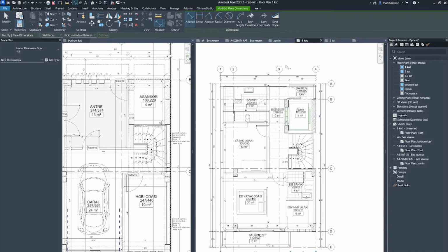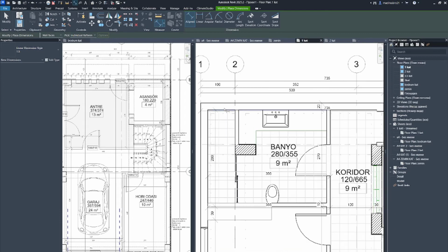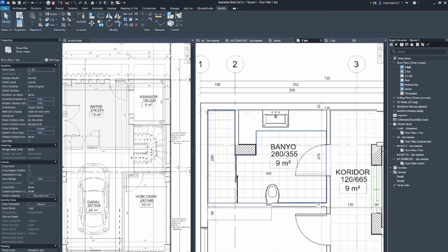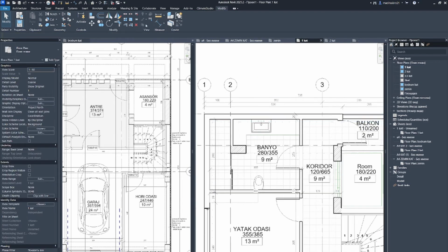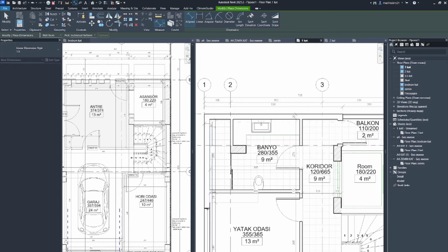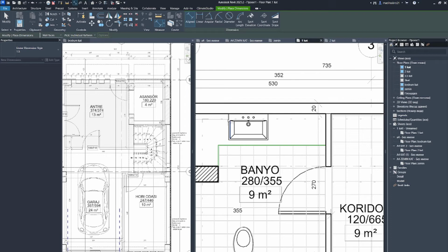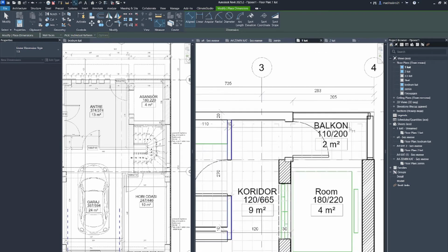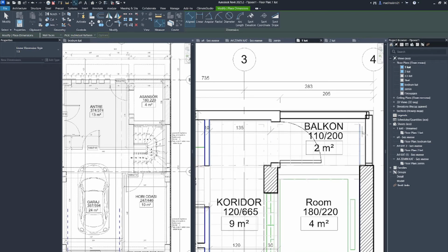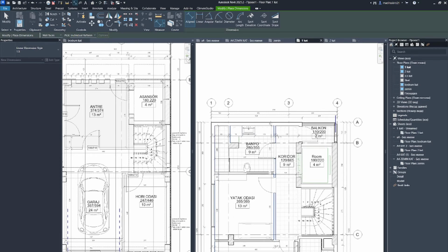Now we're going to go to the inside, internal dimensions. Internal dimensions are also supposed to go continuously and not be divided. So if I start from here, I have to continue. Let's delete this dimension because I didn't like it. Okay, so I choose dimension and it comes and I show the area, show all the dimensions here. I can show these ones too, why not, if I would like to show, of course. Okay, the middle, the glass, and so as you can see, this comes continuously from here.